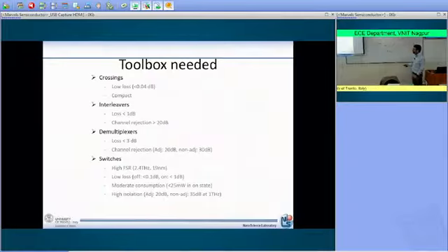And even here, we need to have a very good channel rejection, meaning that the residual power of lambda 12 on the first waveguide should be lower than 30 dBs. Okay? Those are also parameters that we need to satisfy in our design. And then we have the switch.